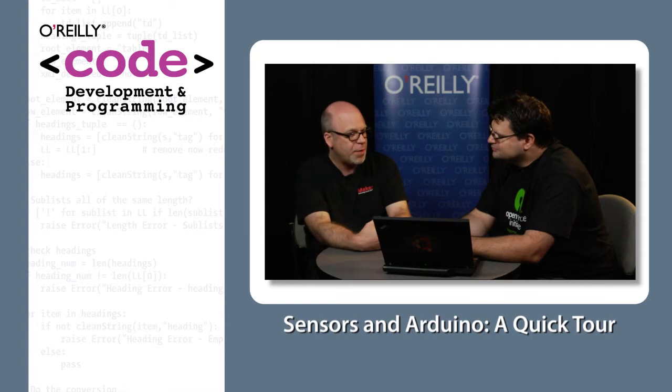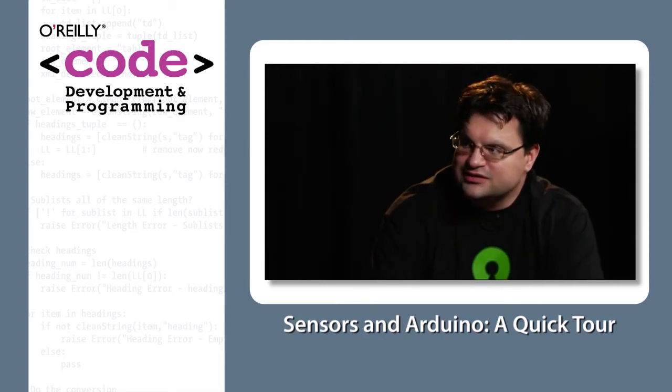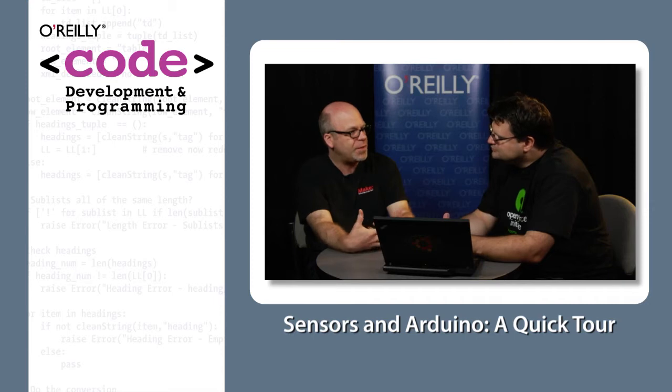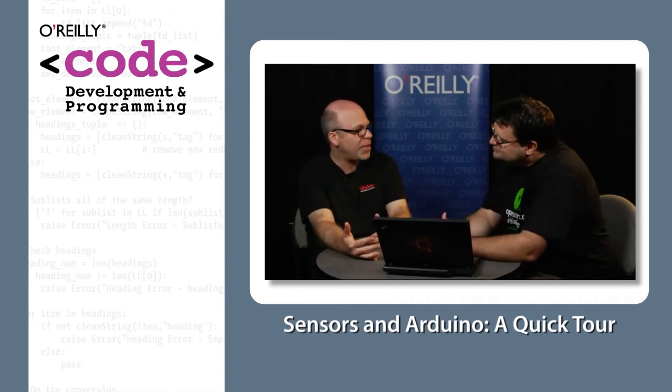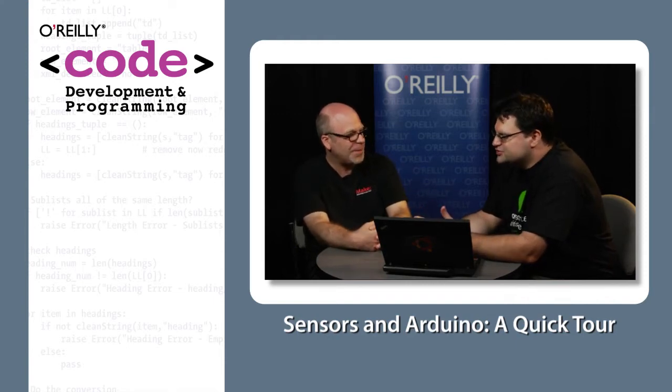That's right. And they also have this ADC, an analog digital converter. And so that makes it very easy. You're literally just writing a couple of function calls and then reasoning on the results of the output of these. And the results are a value. It's not 0 to 5, it's just a number. 0 to, is it 1023 or 256? Well, it depends on what you're looking at.